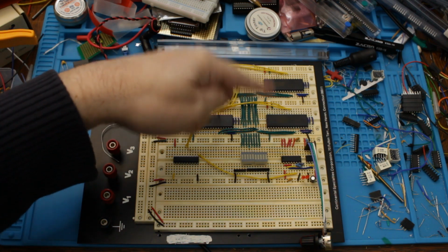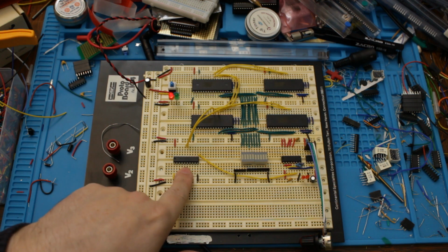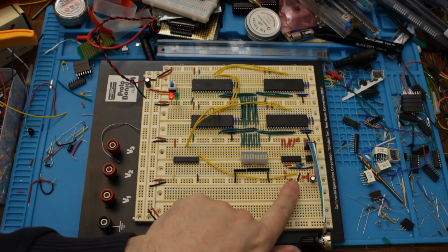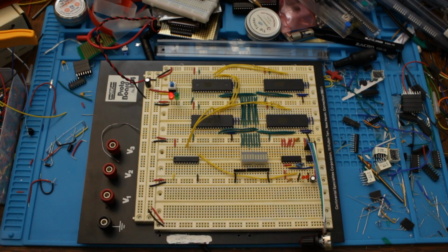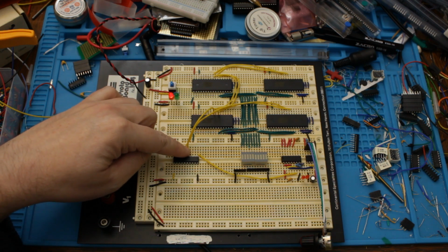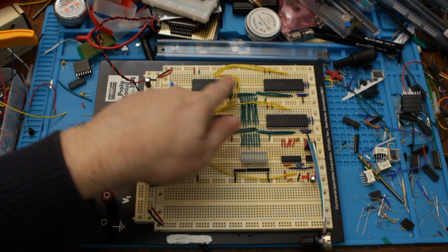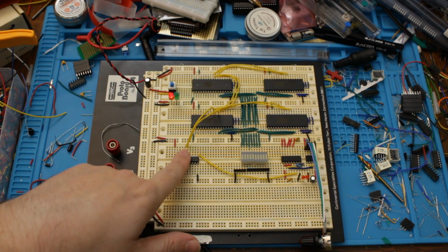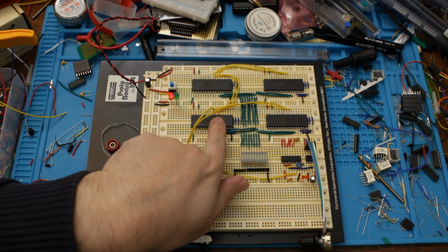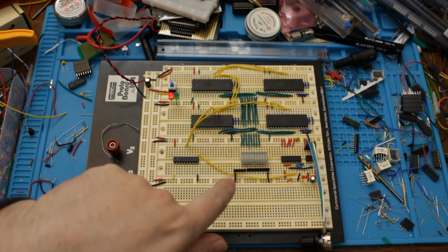At the top you can see the 4 ROMs, and in the bottom left here is the 8-way D flip-flop. You can see that the clock input of the D flip-flop is driven from phase 1, coming from the clock module over here. And I've wired the outputs of 2 of the elements of the D flip-flop through to the control signals on the ROMs, and that's just copied across to all of the other ROMs by these yellow wires. And these 2 are the memory request and the read-write signal. And as I said before, the memory request controls the chip select on the ROMs, and the read-write signal controls the output enable on the ROMs.